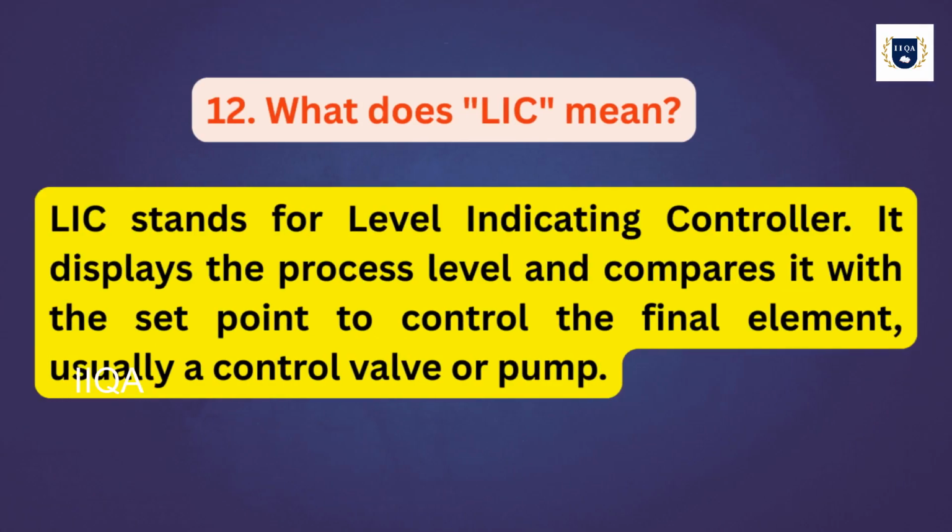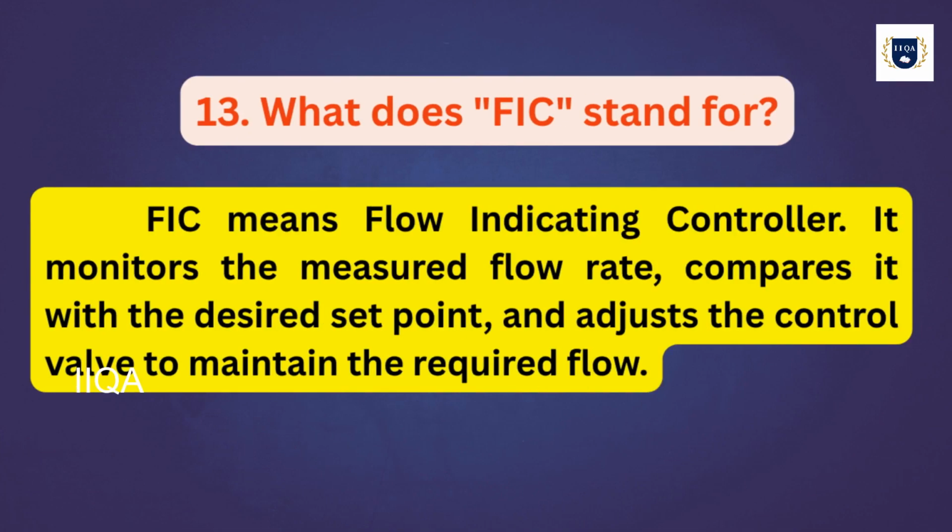What does LIC mean? LIC stands for Level Indicating Controller. It displays the process level and compares it with the set point to control the final element, usually a control valve or pump.